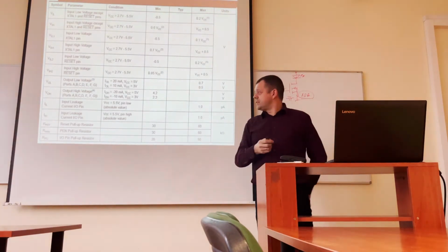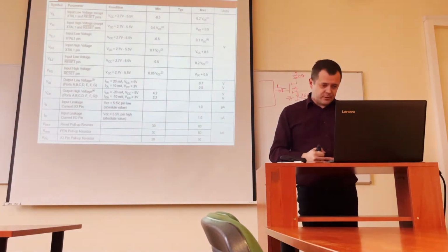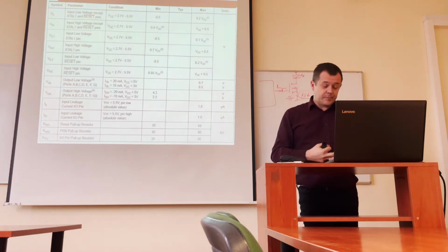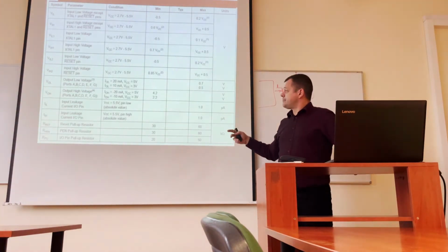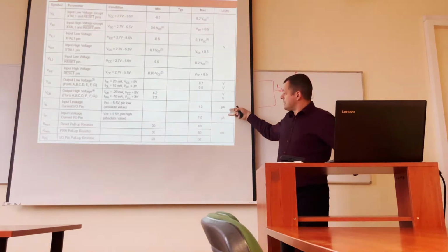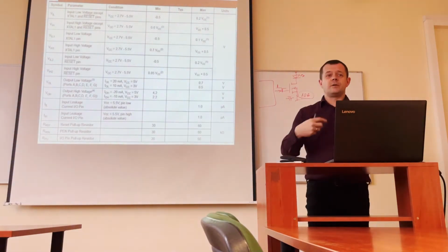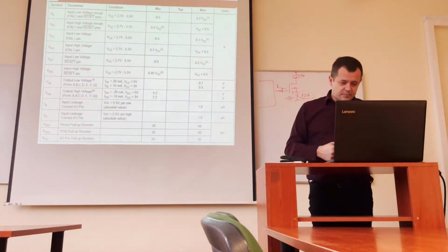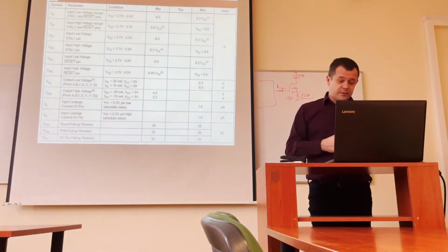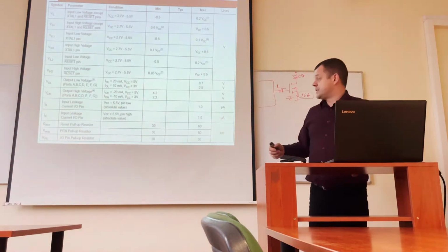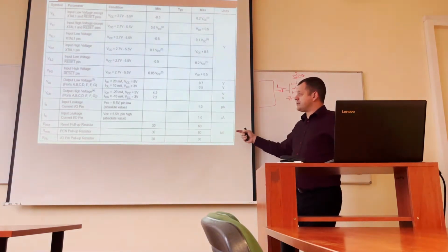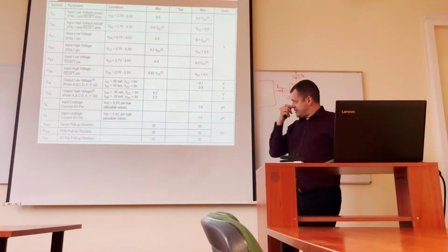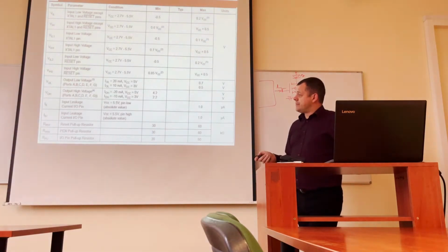This is of course important if we talk about very low power consumption devices. This 1 microamp is not negligible, to be honest, because it's flowing always. Especially if you have tens or hundreds of ports connected, then just 1 microamp can give us a very substantial power drain.